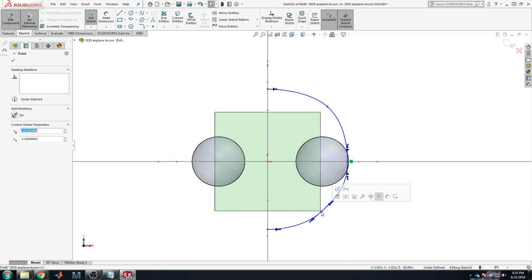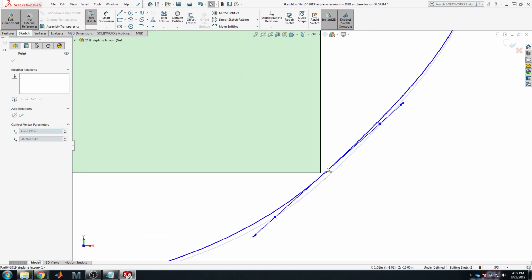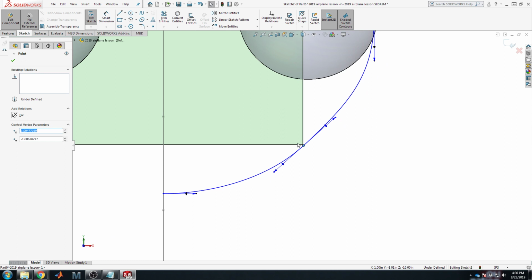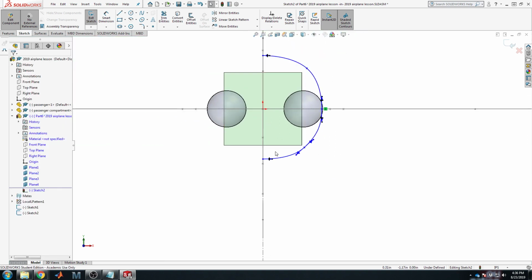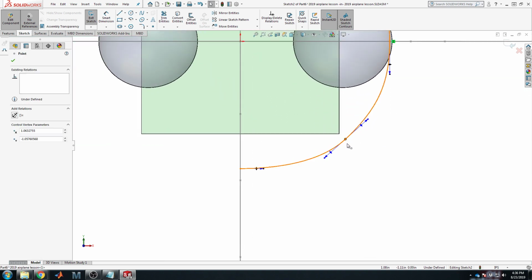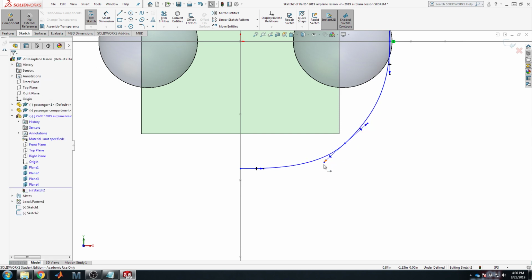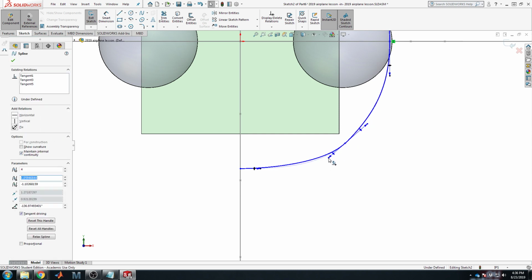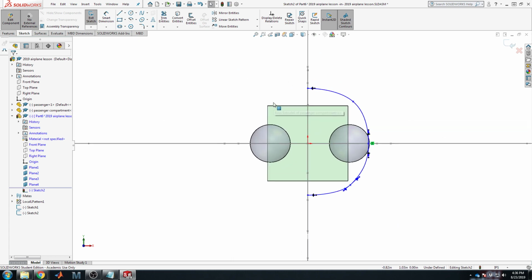Now, here's the thing. You don't want to take this fuselage right down to within 1/100 of an inch of your payload. Because keep in mind, as you make this part, this is the outer mold line. So you have skin thickness, you'll have some composite material thickness, you'll have some inaccuracy of part production you really, really should account for. Plus the difference in drag from here to here is not really a big deal. So make sure it works, first and foremost, please. Let's not go too wild on minimizing things. Let's give ourselves room to grow and to adjust the airplane as necessary.